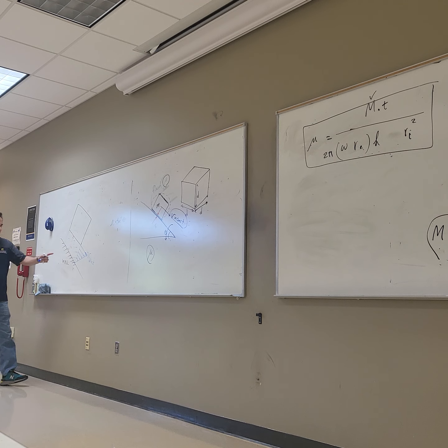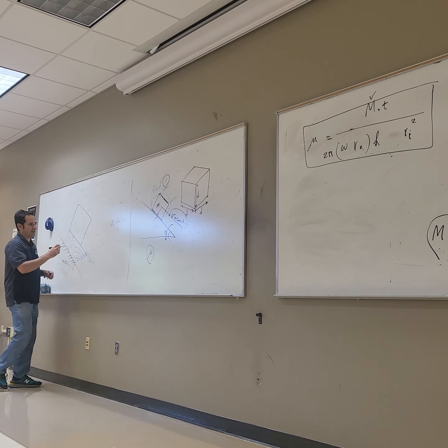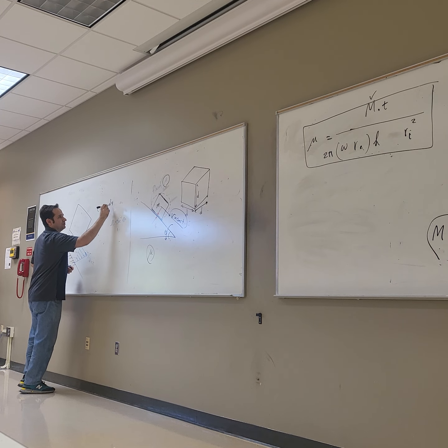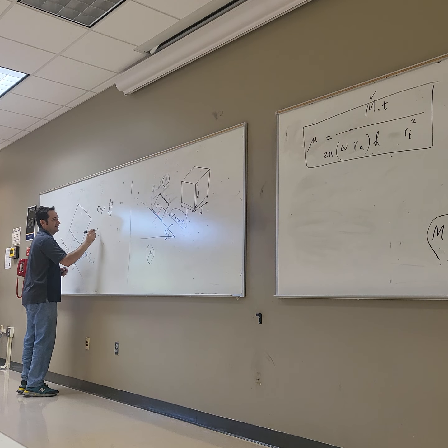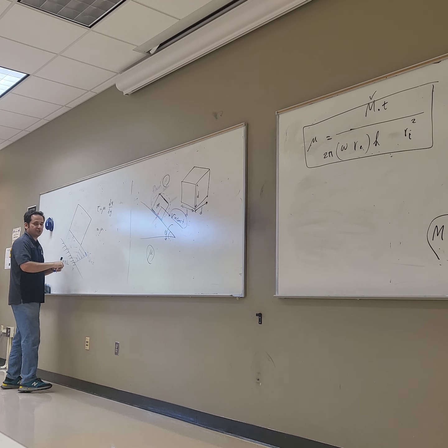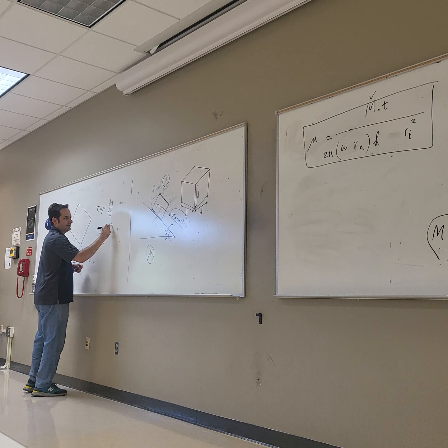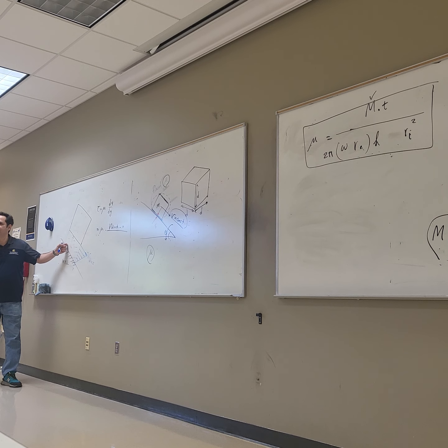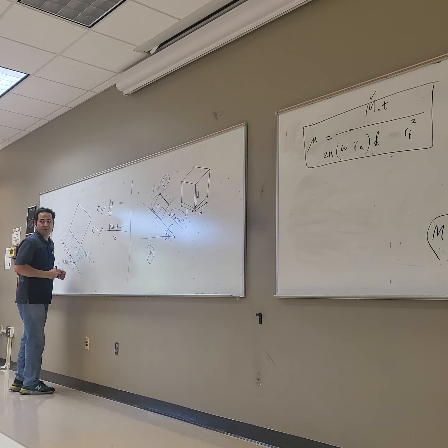So what can I write for the gradient of velocity here? So the shear is equal to what? Newtonian: mu du/dy. For that, I can approximate that. Mu times, what's the change in the velocity? V block minus 0, because the velocity at the surface is 0, divided by delta.